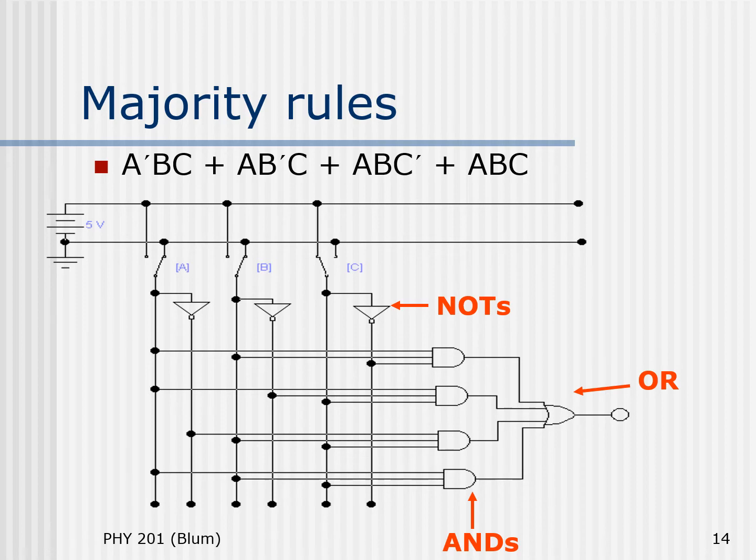At the output of switch A, we have a wire going down from that switch, but peeling off of that wire, we also have an inverter, a NOT gate, that little triangle with the circle on it pointing down. This means that we have access not only to whatever state A is, but if we connect to a wire after the NOT gate, we also have access to not A, or A prime. And we do a similar thing for the B and C inputs.